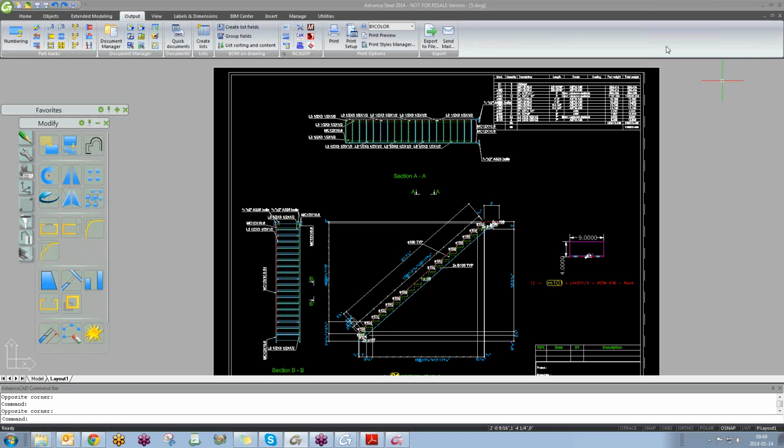All right. Drawing processes, right? Nope. Drawing styles this time. Drawing styles. Okay. On the bottom there it is, Stair Rail. All right. So stair and railing, and then I want to use Main part stairs at UCS. Yep.